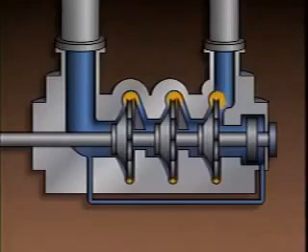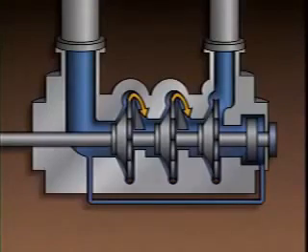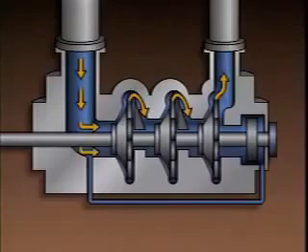In the volute, the liquid's pressure increases. Each of the first 2 volutes discharges into the suction eye of the stage that follows it. The 3rd stage volute discharges into the pump's outlet. So in this pump, the liquid flow path is from one end to the other.